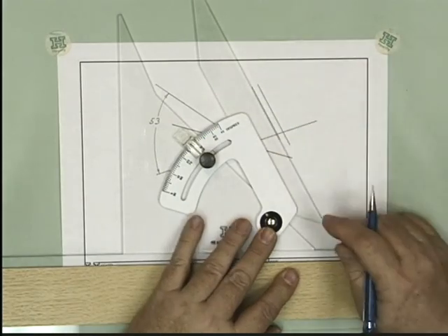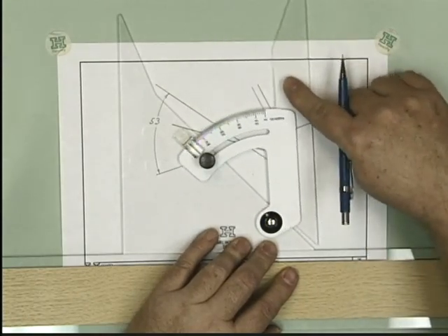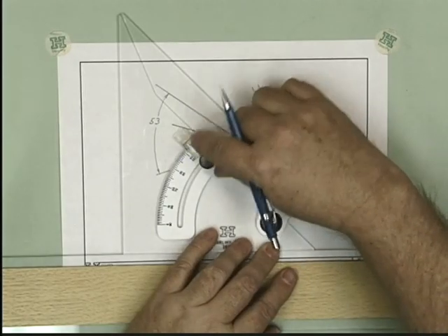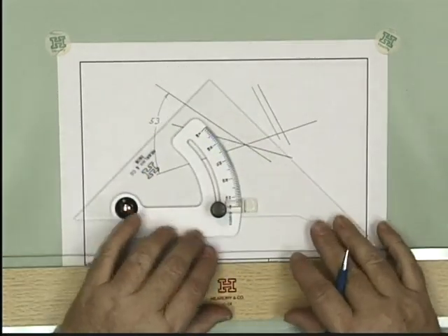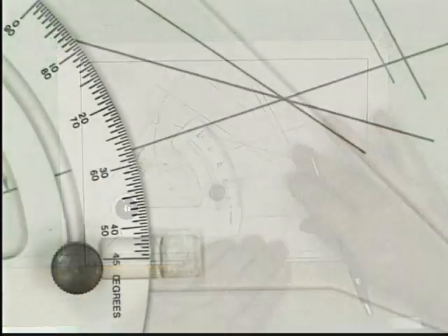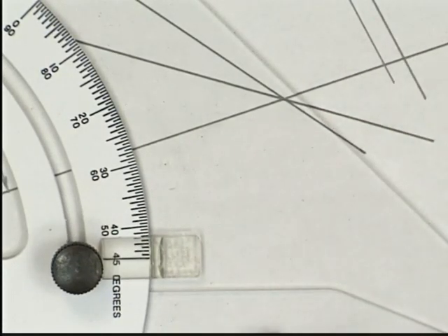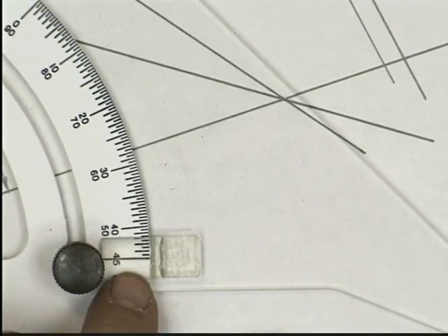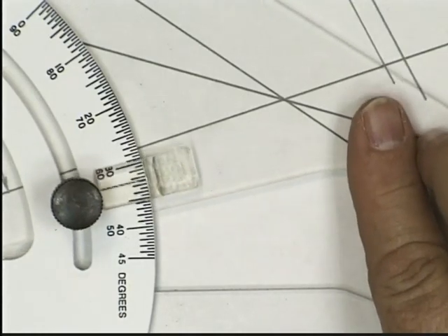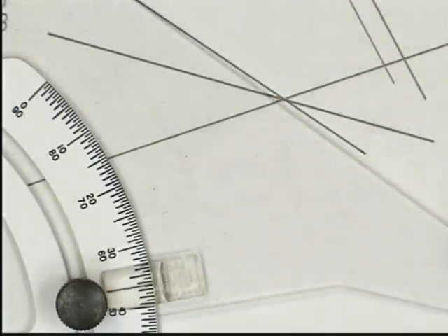You notice though that this only goes from 45 on up to 90. What if you want to make angles that are smaller? Well, you can turn it around and you can swing it this way, or you can use this side over here. Once again, when I slide this all the way down tight, this side over here will be at 45 degrees, and that's what this dial indicator says. Now when I slide this out, I can use a little mini protractor to adjust this, tighten the screw, and then draw lines at the desired angle.